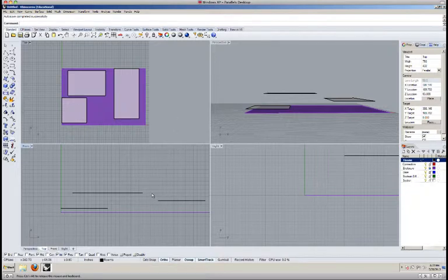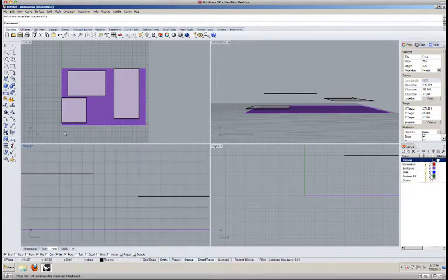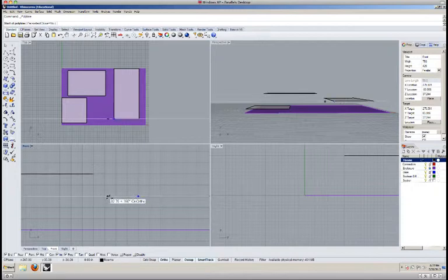If I were to sketch this out in the side view in terms of how a stair is going to work, I'm going to use the polyline tool. I'm not drawing the actual stair, I'm just thinking about how I need to draw it. From this plane, I can count this as my bottom tread. Treads are the horizontals, and risers are the verticals. The part that you step on is the tread, and the riser is the height that you rise up in between each of the steps.